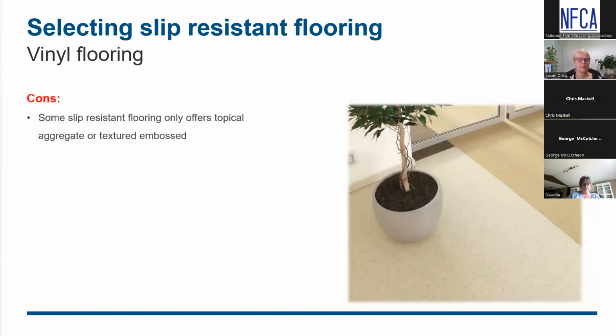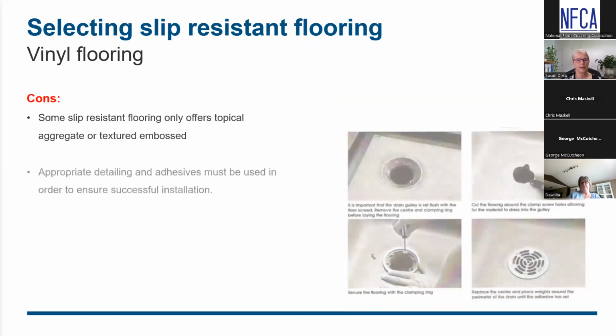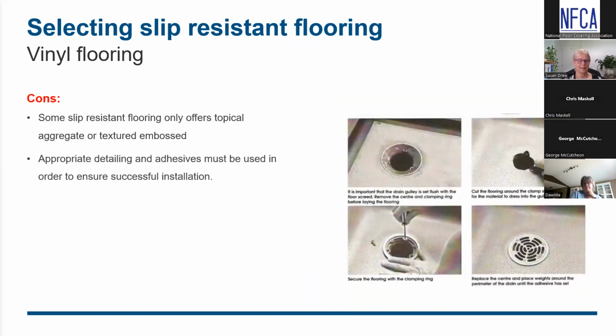Some of the cons is that some slip-resistant flooring only offers topical aggregate or textured emboss. So there isn't that aggregate through and through the material. It requires appropriate detailing. I should have put a drain detail in here, but appropriate detailing and adhesive must be used in order to ensure successful installation.